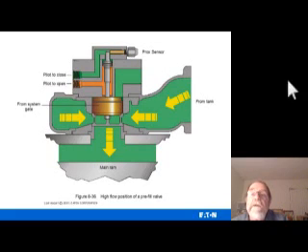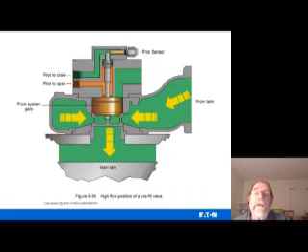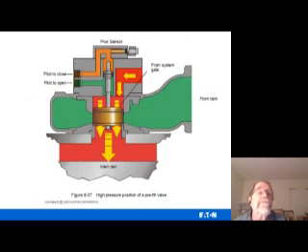So what you have is a pilot to open and a pilot to close, and there's a sensor there. Essentially you use the pilot fluid to actuate this plunger to close or open this device. And once it's activated, it's closed and there's no more fluid flow. It's pushed back down. Go look at that again. You have fluid flow everywhere, and then boom, it stops.